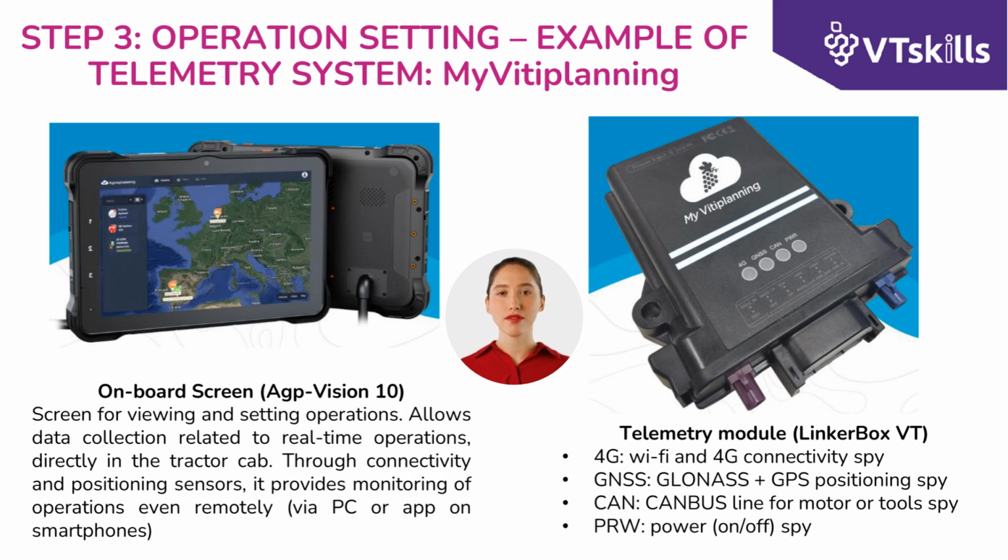Operation tracking is now realized with 4.0 technologies. They involve using remote telecommunication systems between spraying sites, web platforms, local monitors, or smartphone apps. Communication is carried out via GSM GPRS modems using geo-reference data packets containing tractor and sprayer information. Generally, 4.0 systems also allow for remote interaction so that the operator on the farm can communicate in real time with the operator in the field in the event of machine malfunctions being detected.